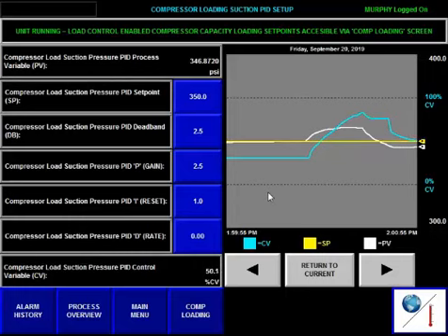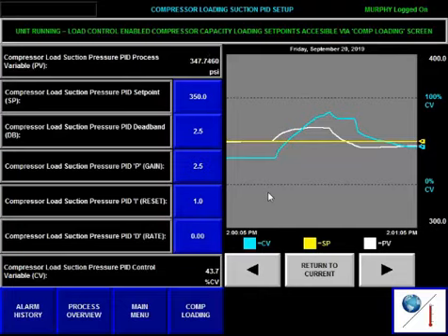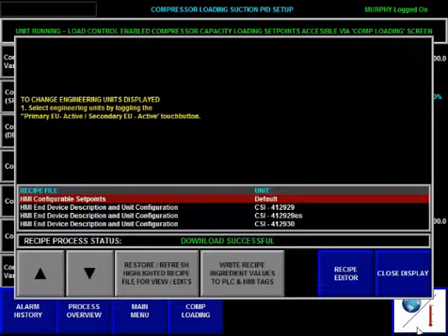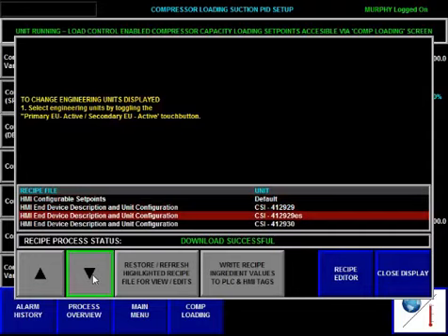You can see by looking at the output curve, a small disturbance occurs when a cylinder loader engages. Shortly after the loader engages, you see the PID is tuned properly so that the output flattens out right away.